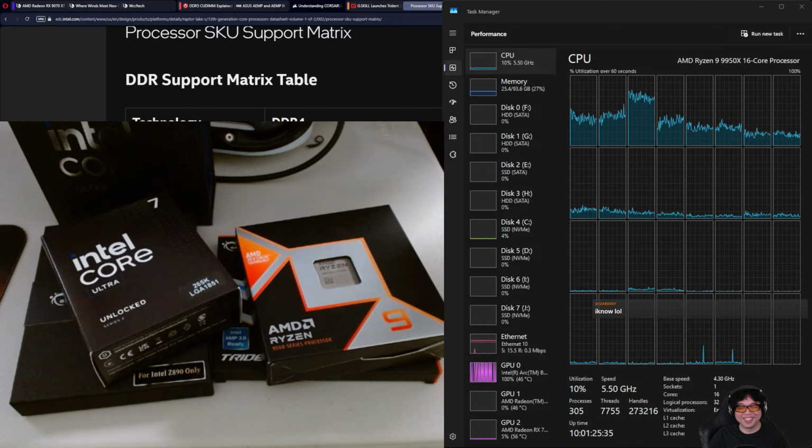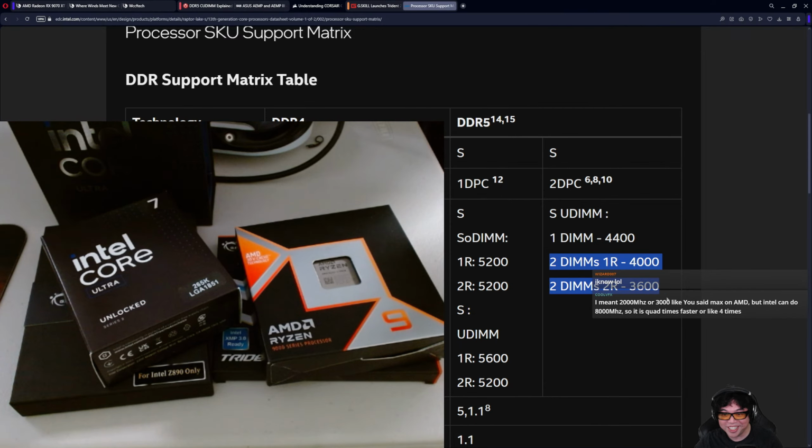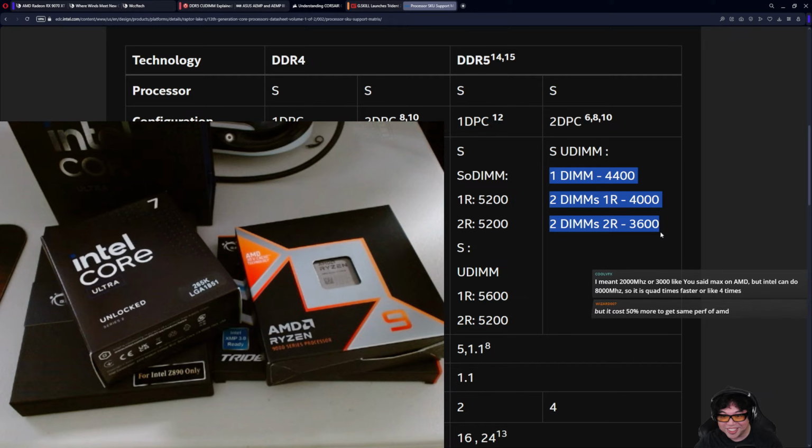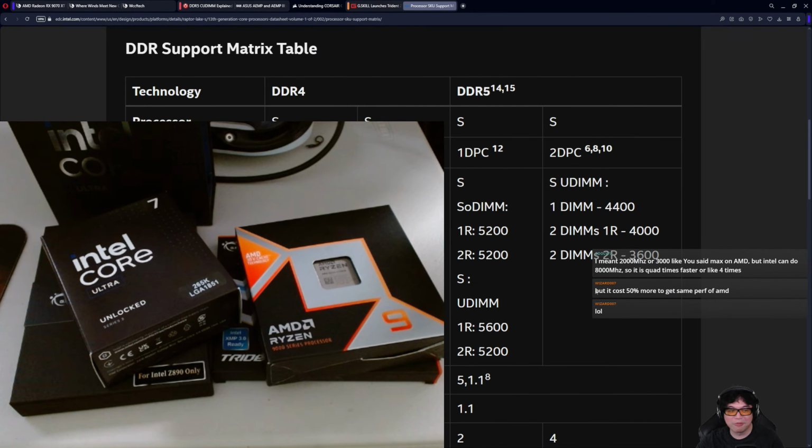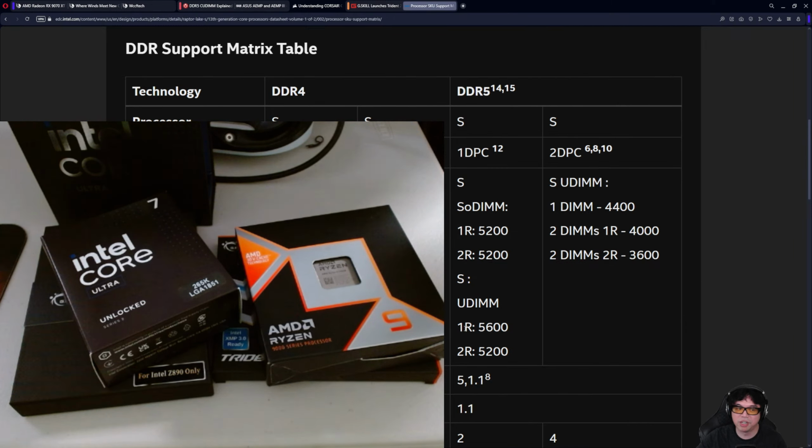Seriously, dude, it's literally on the screen. It can't lift. Do you see these official speeds? These are DDR5 speeds. Oh, and by the way, single rank, 5600 is the maximum supported speed on an actual UDIMM. Now, Arrow Lake is superior in that regard. Arrow Lake is rated for up to 6400, so it is better than 13th gen. 13th gen is the dumb. Don't be the dumb. That's all I can say. Dude, very disappointing stuff.